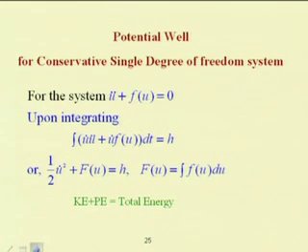So, we can study the nonlinear system by using qualitative method or quantitative method. Let us study this by using a qualitative method. In this qualitative method, let us consider a conservative system. In this conservative system, I can write the equation of motion of the system to be u double dot plus f(u) equal to 0. If you integrate this equation, let me multiply u dot to this equation.